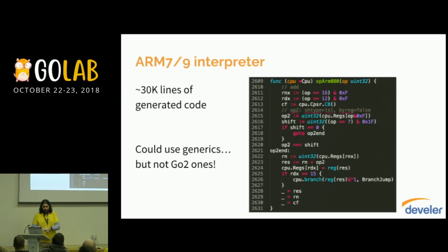And then, of course, you need to write the actual opcodes. And ARM is a very complex processor because it's got 2 instruction sets, not one: the ARM instruction set and the Thumb instruction set. And each of them has many opcodes which are CISC-like. They have many, many variations, even a small variation, like you can have an addition with flags, without flags, with a barrel shift, without a barrel shift. So it's a really complex instruction set.